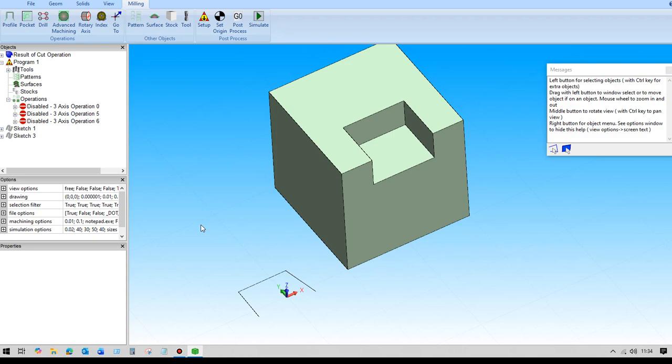In this video, we'll show you how we can handle pocketing on open pockets. As you can see here, we've got a couple of simple shapes. Supposing we wanted to pocket out this area here, it's open, but it's based on a 3D model, so therefore it will know the extent that it's able to machine. In this example here, it's a 2D wireframe, so we'll need to do something a bit different there.